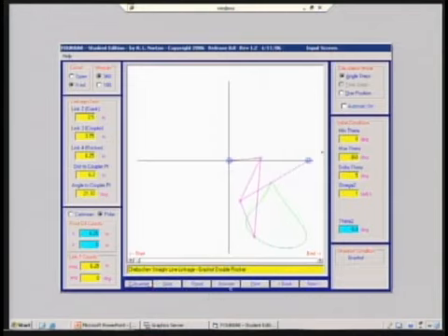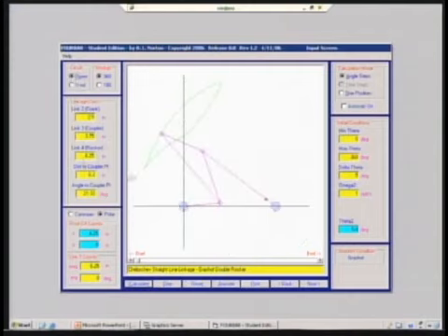And that doesn't look an awful lot like the curve that I saw in Hrones and Nelson. But you'll notice that this is in the crossed mode up here in the upper left-hand corner. And if you've read Chapter 4 yet, which you may not have at this stage of the course, I take a couple of curves up before we get to that business. But let me just tell you that a 4-bar linkage can be assembled in one of 2 modes. I call them open and crossed. And it's not possible to predict which you have at the outset.